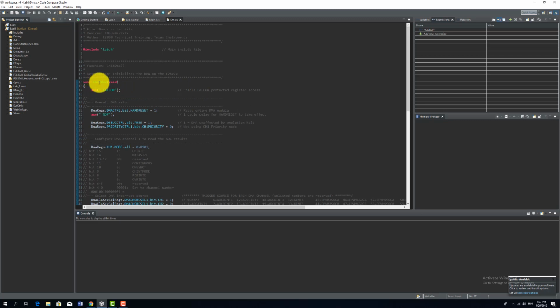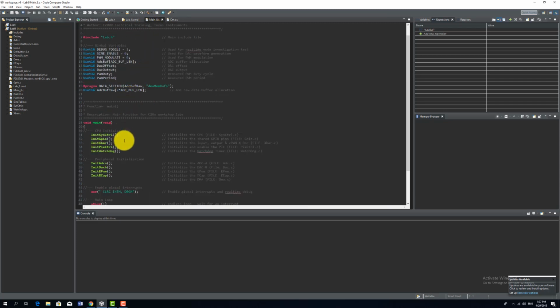Initialize DMA is a void function, a replacement for your main function, because in this DMAC file, this represents the initialize DMA function loop. So let's go back to your main, and we have to check it here under the peripheral initializations. DMA initialize remains blank, so we have to put it here: init DMA, followed by 2 parentheses and then a semicolon.